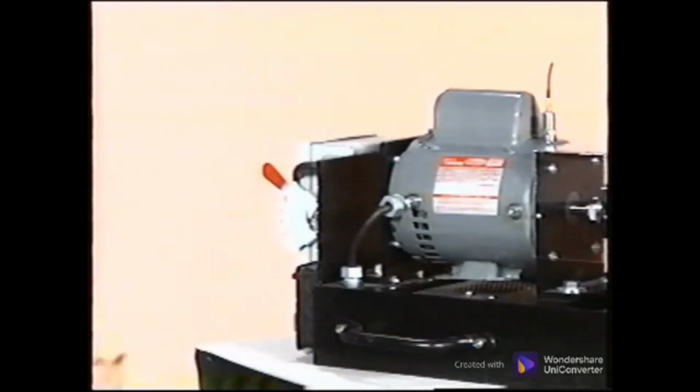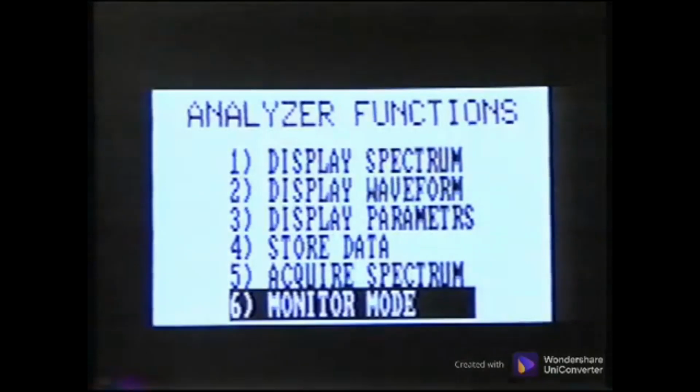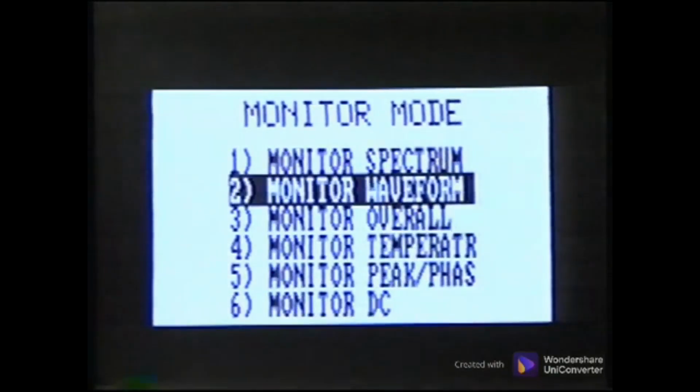A technique often used to determine the amount of energy attributed to electrical phenomena is to shut off the power while monitoring the data. Electrical energy will immediately drop out, while mechanical energy will remain through the coast down. The coast down can be monitored in the spectral or waveform data.